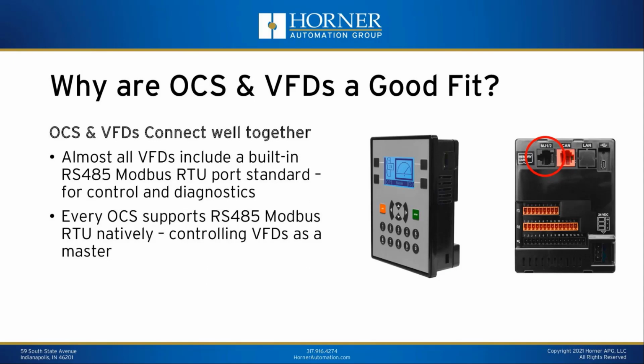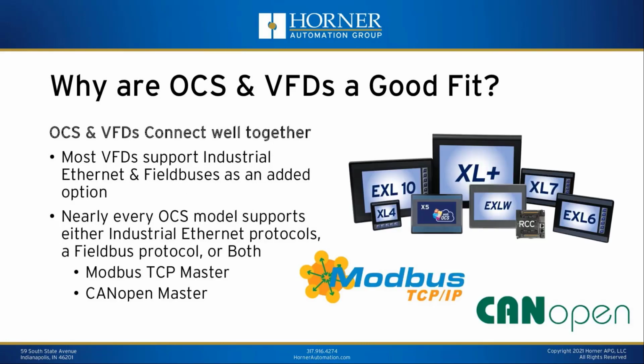And then not only can you control a VFD through I/O, you can also control it using RS-485. Typically, in the lower cost models, that is through Modbus RTU protocol, and that communications port is standard in every OCS that we sell. So again, another reason we've got a good fit there. In addition to the basics of Modbus communications, we also support some slightly more advanced communication options, including communicating over Ethernet for those drives that support it, as well as CANopen for those drives that support it.